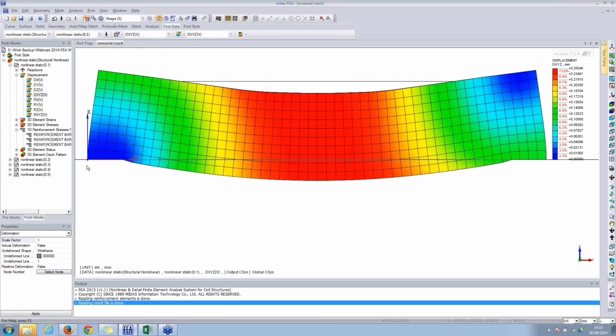You can also model some plate elements or some solid elements, some wood block below the support points, and then apply the boundaries at the bottom of the wooden blocks to make the stress distribution more realistic.